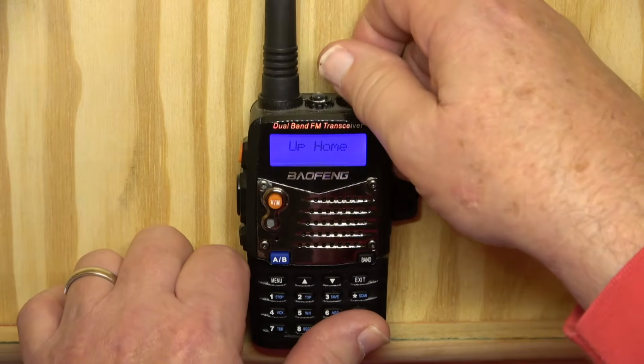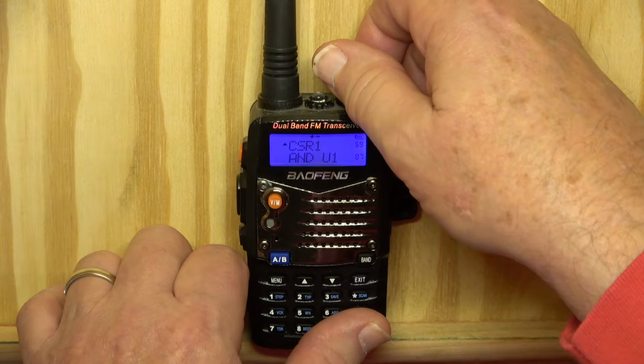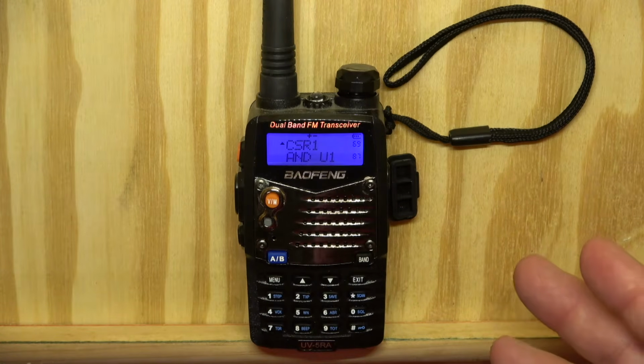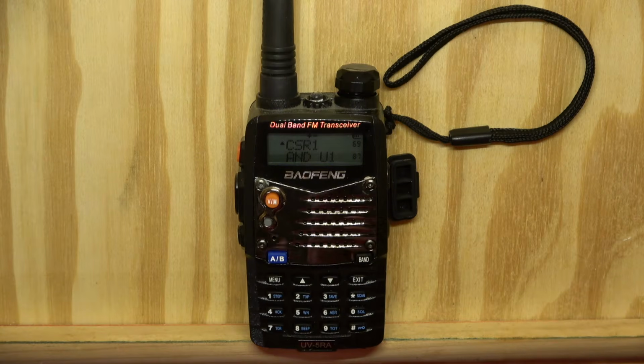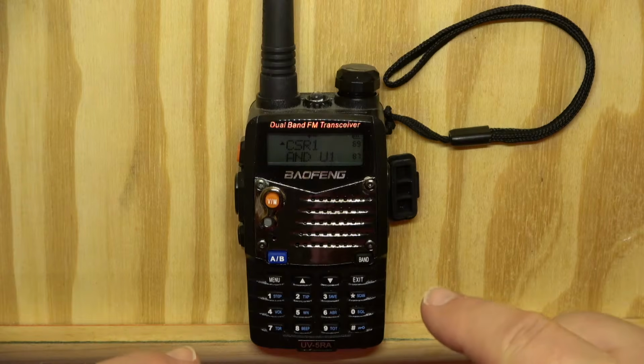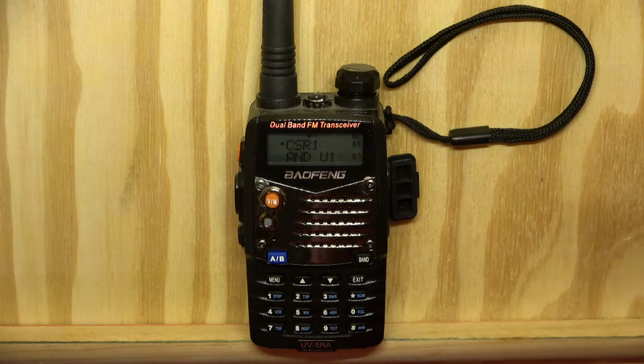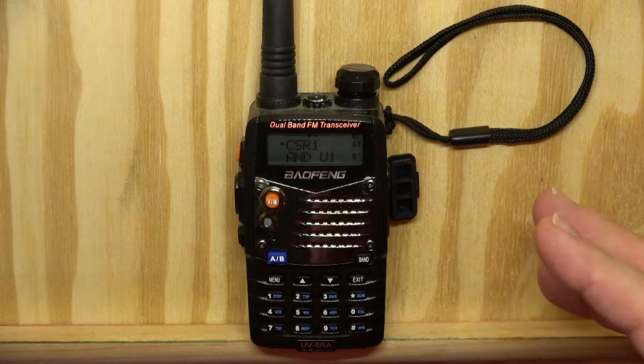I got a bunch of these sitting downstairs, all right? I'm not going to transmit on it, but right now the radio is just sitting in receive, and it's nice and quiet. We're not hearing anything. That's because the carrier squelch function is working in this radio. There's no transmission coming from the repeater. It's tuned to the Caesar's Head repeater, but there's no transmission coming into it right now.